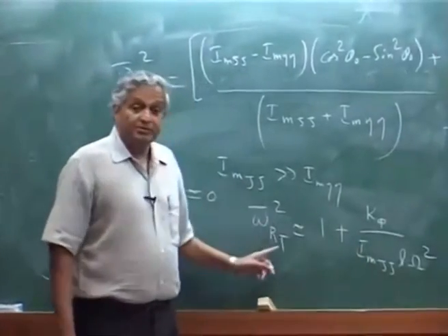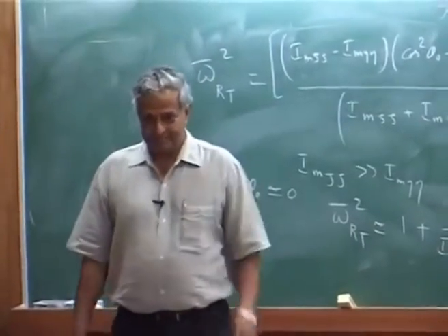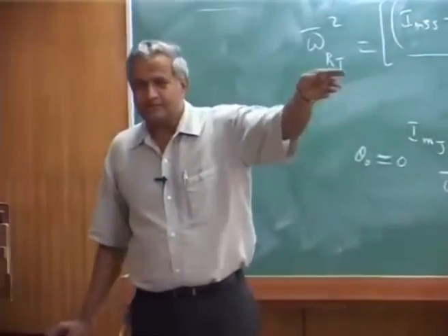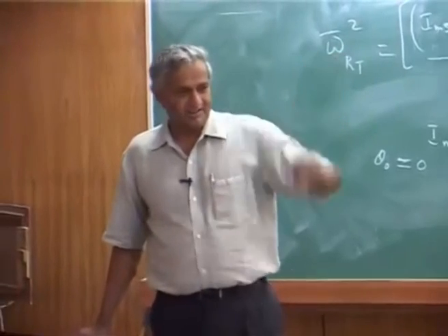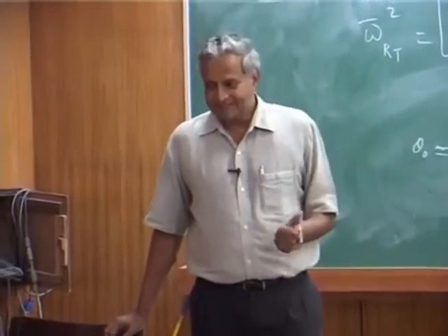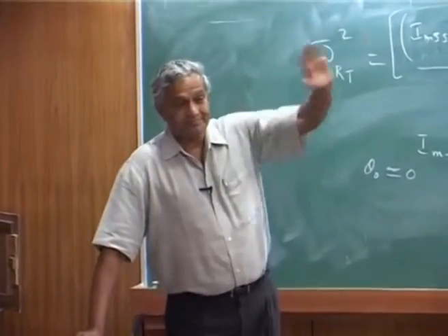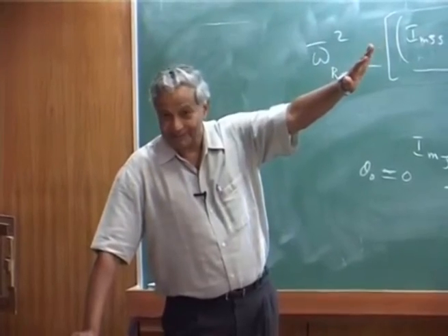Where do you place the frequency of the torsion? See, flap is around 1.09, 1.04, 1.03, like that. Lead-lag is 0.25 or 0.7, non-dimensional. Torsion, you want to keep far away.